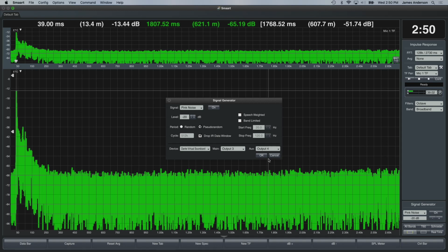Then they realized they didn't like the A to D converters on it, so they got a different chip to do A to D than D to A, but they weren't on the same clock. People that did this type of measurement, and you also hear people talking about MLS measurements, maximal length sequence, found that the output and the input weren't on the same clock, and so doing those types of measurements with that early device caused problems.